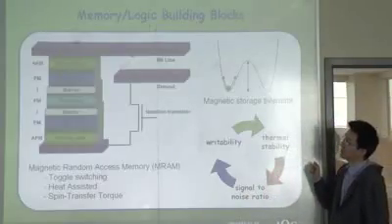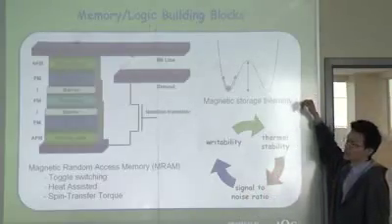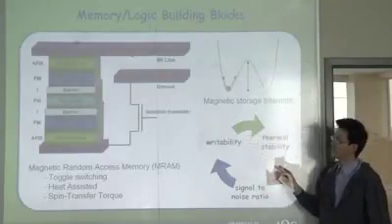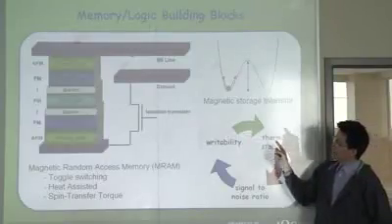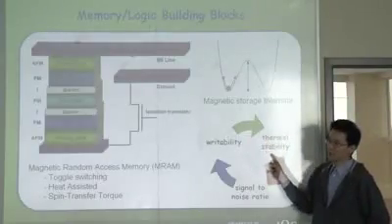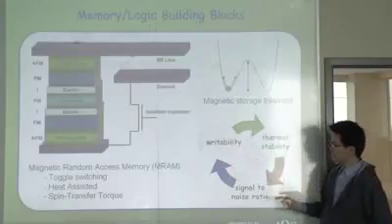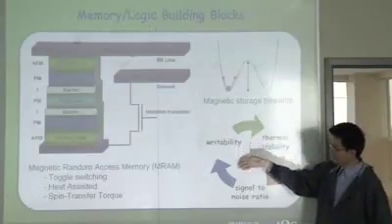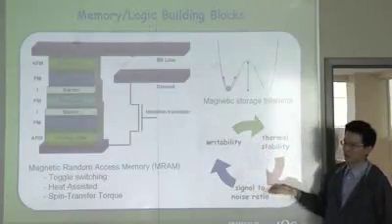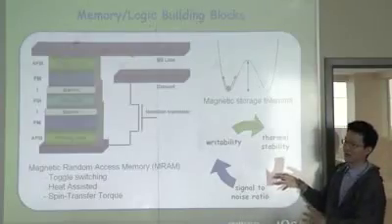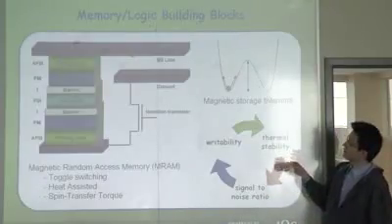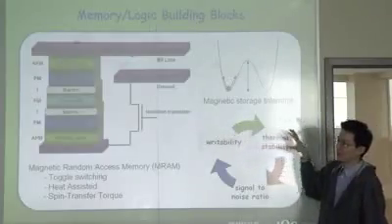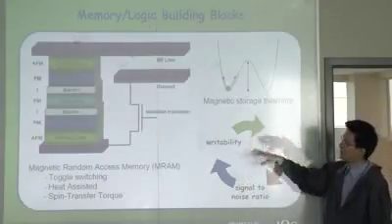I just want to mention the so-called storage trilemma. There are three fundamental problems, and they are totally tied to each other. If a system is so stable, you will have a hard time writing it. If you address this stability and writability problem, you will run into a problem with the signal to noise ratio, which will typically require a large volume to reduce the noise. So we normally refer to this as the magnetic storage trilemma. When you solve one problem, you run into another. You create more problems. It's always like that.